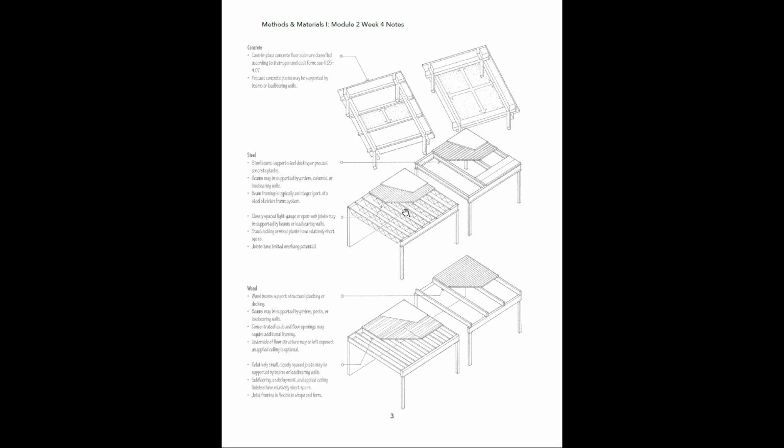Okay, so we also talked about that, but that is our corrugated metal decking, and it's kind of like a U shape or a W shape, but it's just a series of corrugations. So that's installed directly over top of the open web joist system. Then on top of that is where your actual concrete is going to be. And this concrete is either going to be maybe precast, or it might be poured in place. But basically these are the layers that are making up that steel floor system.